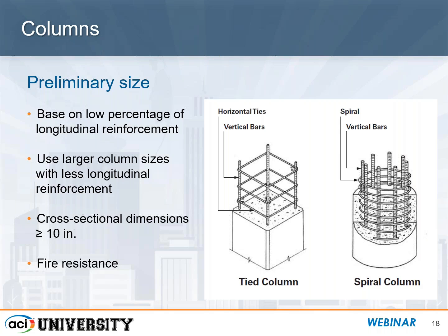Now, we're not covering seismic per se in our two sessions, but there are minimum dimensions if the column is part of a special moment frame, which, as you know, is required in seismic design category D and higher. They do give a minimum cross-section dimension of 10 inches. That's one of the requirements.